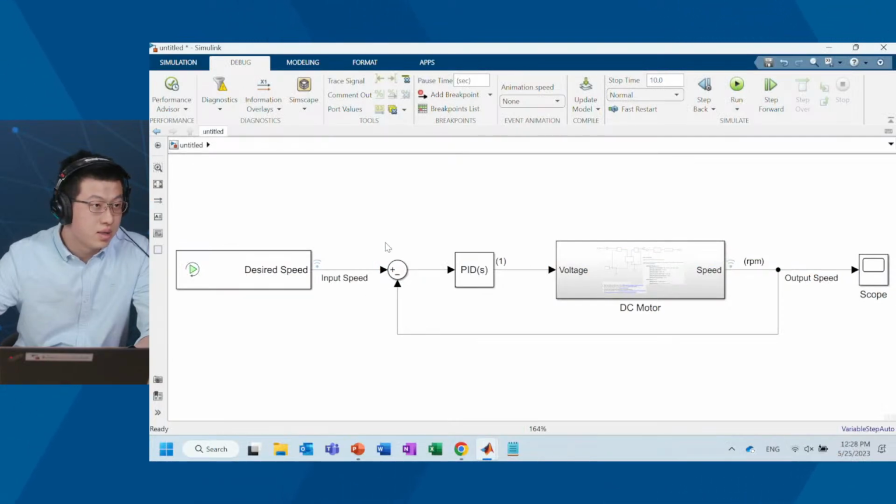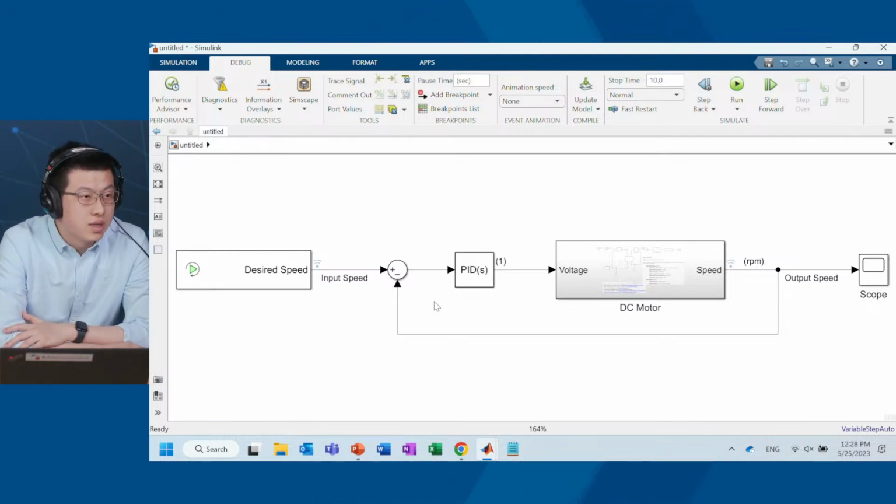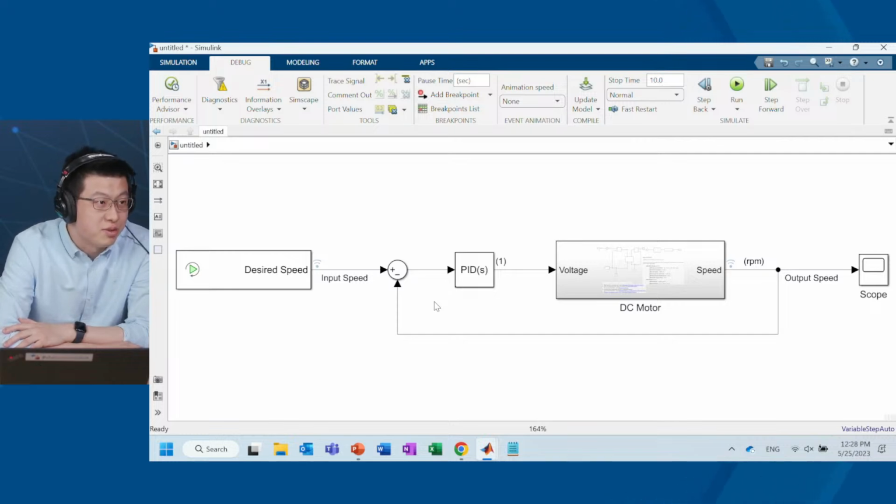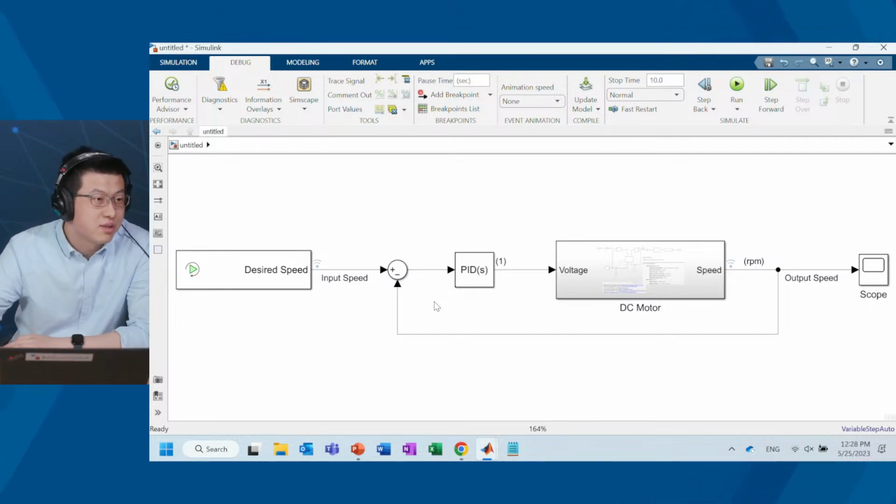Okay, so I think we might need a unit conversion block to showcase the units just before the DC motor. So we can put 2 blocks, one after the PID controller and one before the PID controller. Yeah. So we're able to specify the units of the signal, so not only the quantity it represents, but also the units that the signal represents, right?